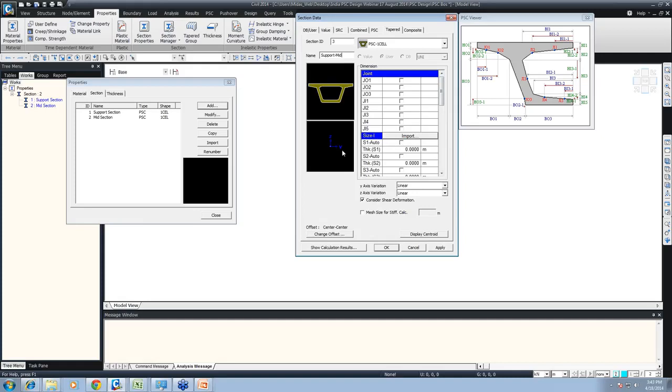Okay, now what do you mean by size I and size J is that majorly my modeling philosophy that I am doing is that I create a node first, right? I create a node at one location first, I create a node at another location, and then I create an element from first node to the second node. So suppose this is my first node and suppose this is my second node. Okay. So now the modeling philosophy is that I am creating my element in this direction. Okay, so my software automatically understands that this is my ith end and this is my jth end. Okay, so I have to taper it from the ith end to the jth end.